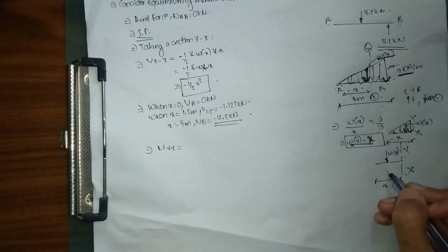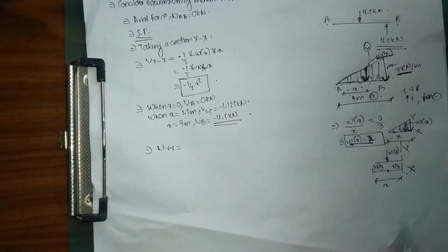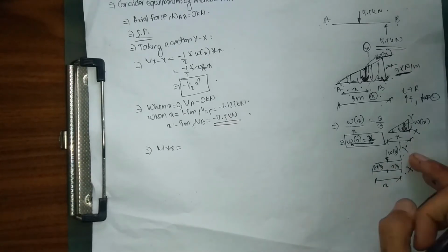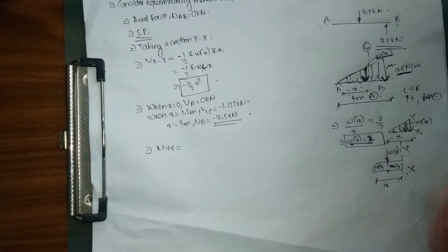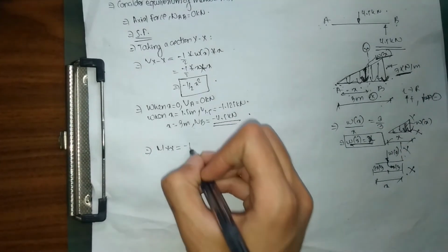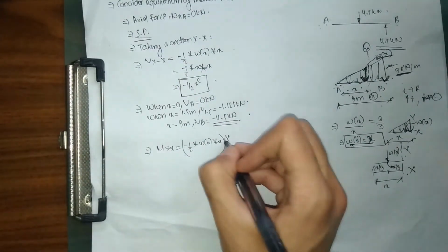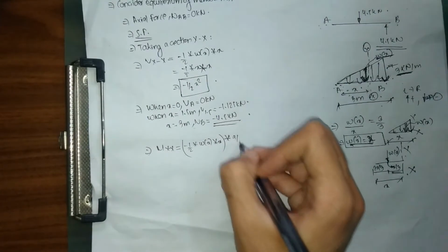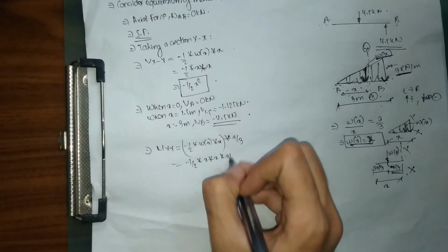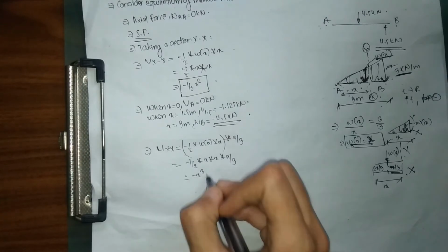So which means this Wx will act at a distance of x by 3 from my shortened section xx, and 2x by 3 from its shorter side. I will explain this before. So this Wx with respect to xx is going to produce anti-clockwise moment. As you can see here, it is pushing downward. Downward means anti-clockwise moment. So simply put this way, minus 1 by 2 into Wx into x. I have converted into point load, and it's at a distance of x by 3. So it's going to be simply equal to minus 1 by 2 into x into x into x by 3, which is x cube, minus x cube by 6.